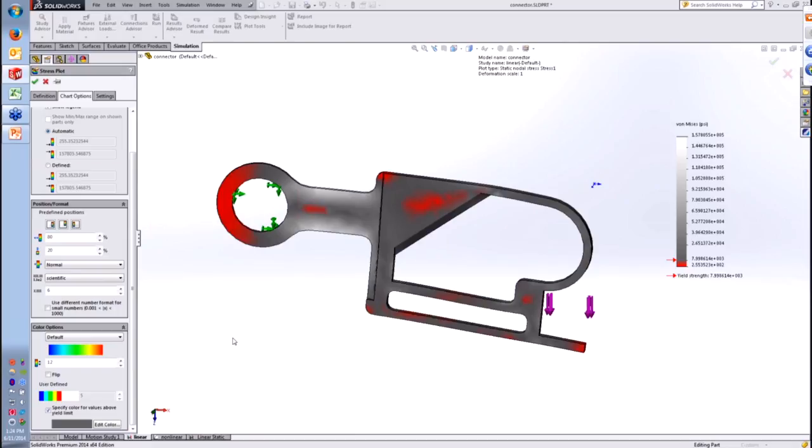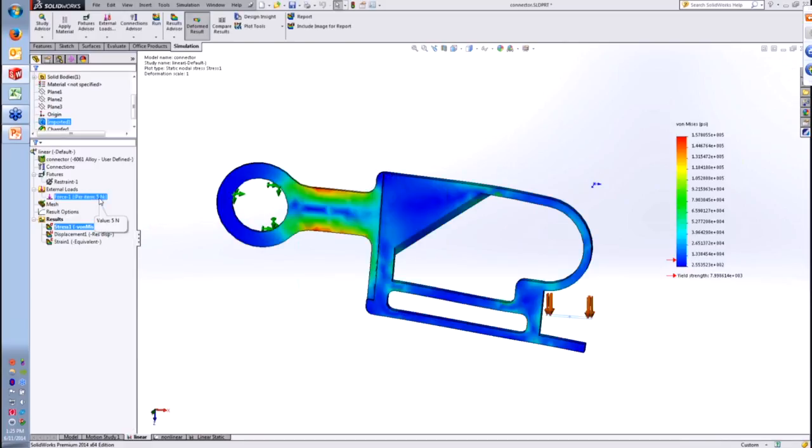Now that may not seem quite right, or even if you don't know, you can tell that just having a stress value that's more than 10 times above the yield probably doesn't sound quite right, because that most likely is also above the ultimate strength of the material, meaning that the part would probably be completely breaking in pieces at this point, with cracks or fractures all over it. And again, this load value that we put in is only 5 newtons, and that may not seem quite right. And if you had that suspicion, you're actually correct.